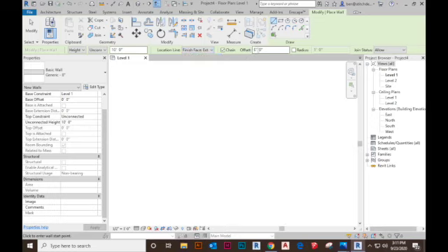You can also offset a wall, which means when you draw a line, that wall will offset that distance or that dimension from the line that you're drawing. You can also select to join your walls by a radius instead of a right angle, and you can determine the dimension or diameter of that radius if this button is selected here in this field. You may also choose your join status for walls to join automatically or for walls to not join at all, allowing or disallowing the join.